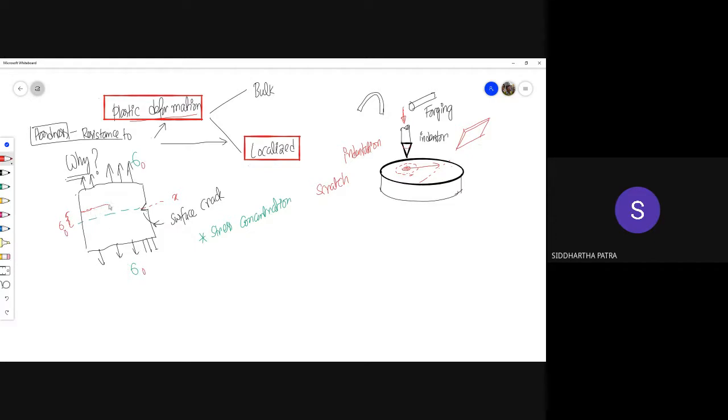But as you get very close to the crack tip, the stress, if you use an elastic model, ideally goes to infinity. And why is that? I'm not saying it ever goes to infinity, but ideally it should, because no material can withstand an infinite amount of stress. We'll look into what happens essentially. But ideally, it predicts that at the crack tip the stress becomes infinite. That's a theoretical prediction based on the elastic assumption.